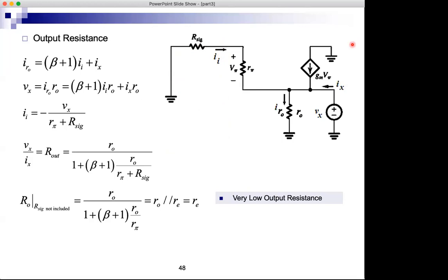We were used to saying that the benefit of using BJT is a large gain. In this case, both. So is there any benefit? No, the large gain of the BJT, we see it in the common emitter and the common base, not here. The gain is less than 1. So there's no advantage of using a BJT over a MOSFET if we compare common drain and common collector.